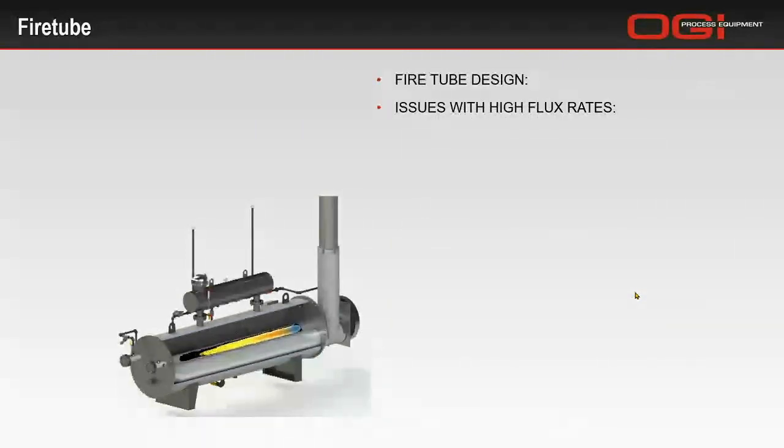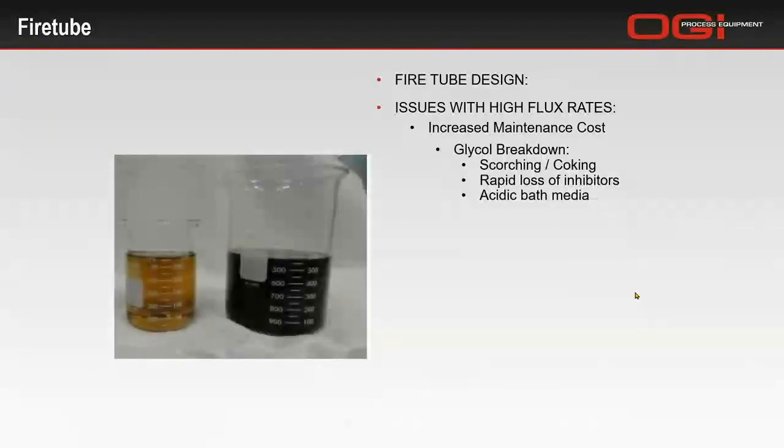And we've got this smaller under-designed heater, we would call. You save money on your capital expenses, but now you're going to have to spend money on your operational expenses. And those specifically will be with glycol breaking down. You're going to lose your corrosion protection, your rust inhibitors. Your bath can turn acidic, and over time it actually could turn into this dark coffee-looking glycol and turn into sludge that will be sitting at the bottom of your heater.